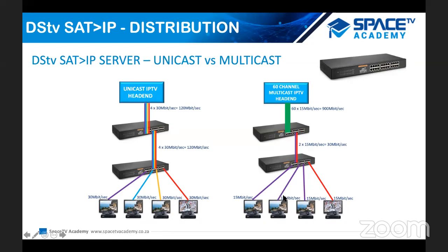If a second guest logs in and selects the same channel, this decoder is going to query and find the information, which you will then see. It looks at the first switch, and because the first guest is already watching, that stream is present on that switch, and it actually just shares it. You will see that there's still only one feed coming down from the main switch, and the same will happen when the third guest logs into that same channel once again.